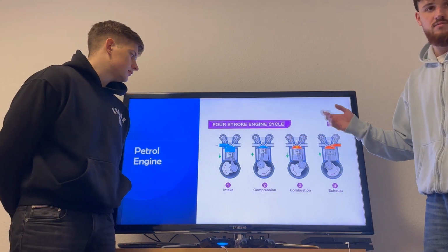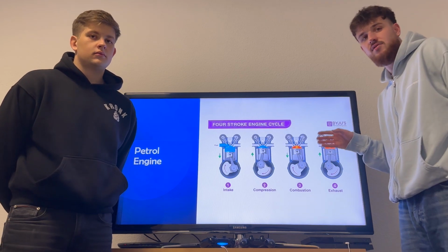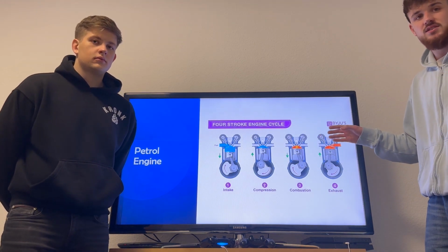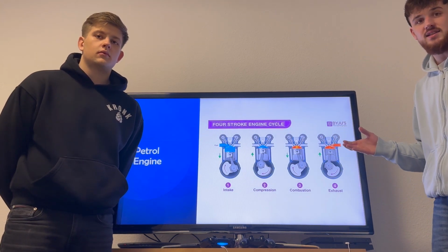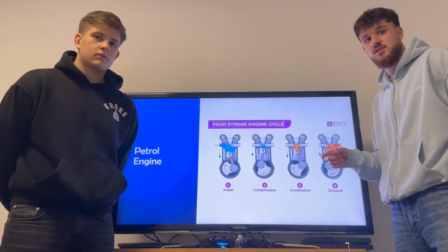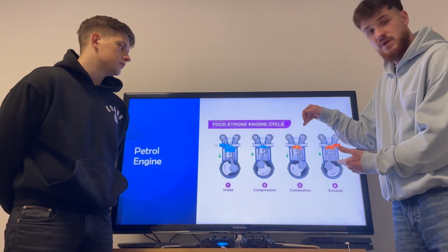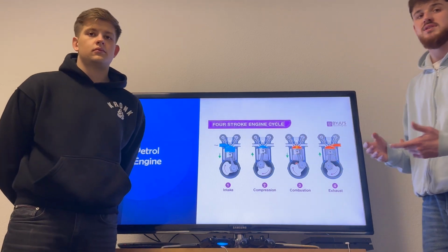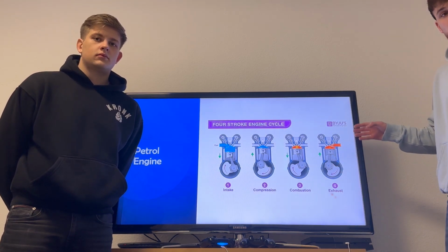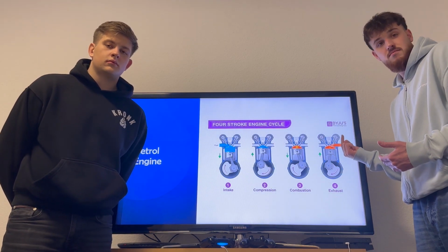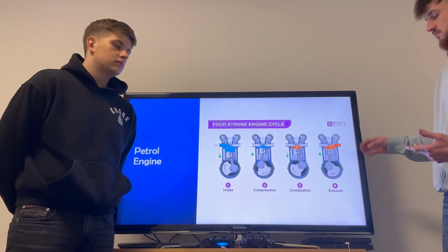Now on to the important step. The air-fuel mixture, or in case of a direct injection, the fuel, gets injected shortly before the piston reaches the upper dead point and ignites the compressed mixture shortly after. Because of the following explosion, or so-called explosion, the piston moves back downwards, and that's the time where the piston generates torque. The last step is where the piston moves back upwards, emitting the exhaust gases into the exhaust system, which we will discuss later.